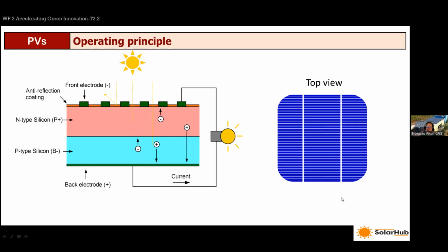If you take a monocrystalline silicon cell, it would look like this, pretty much. You could see the grid on the top surface, and there is also some coating material that does not allow reflection. It at least reduces the reflection of the light, in order to exploit as much as possible the light that is incident on the surface.